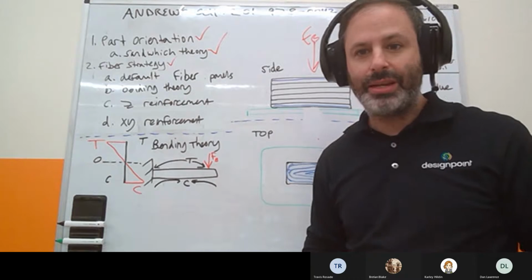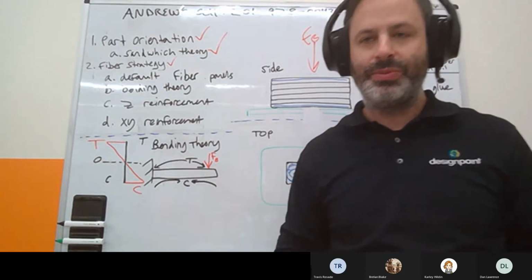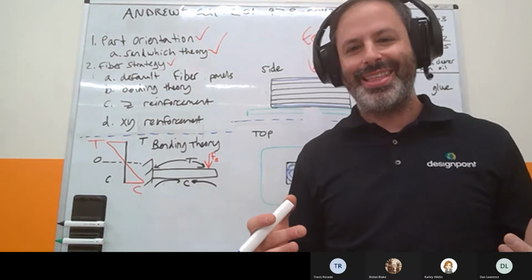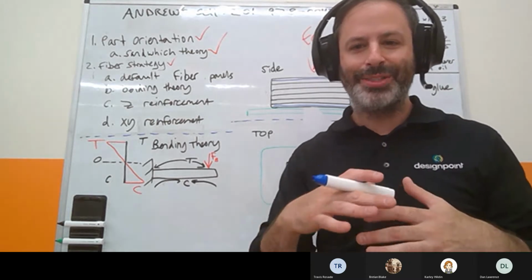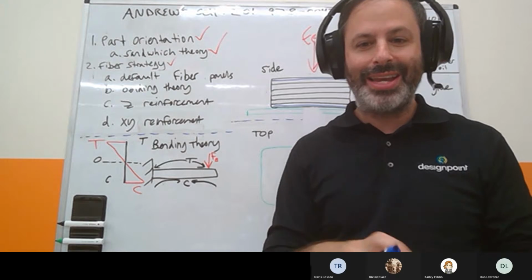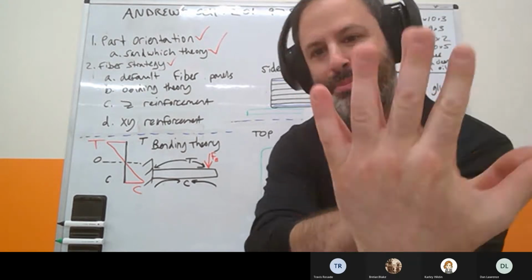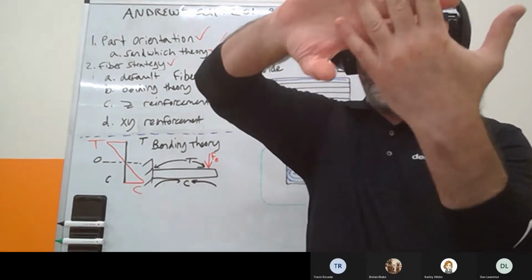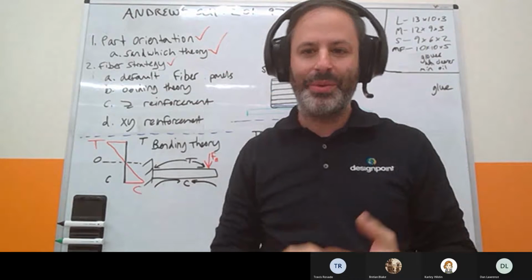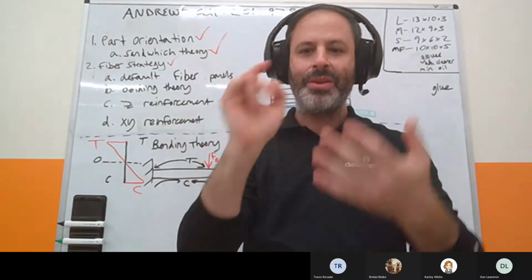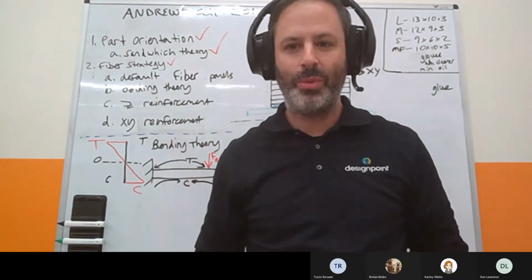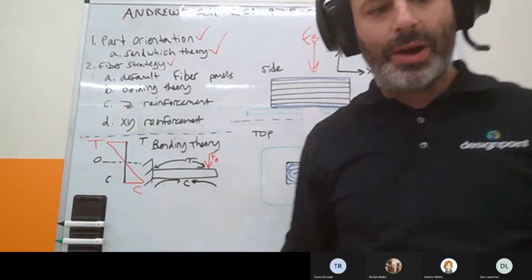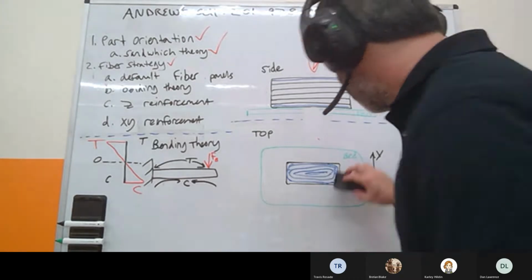And the way that I like to think about this is, think of yourself as a trapeze artist, right? And the fiber panels are your net. So do you want a net that actually lines up perfectly like that? Well, no, you might fall through the net, right? You want the net that's cross-hatched. So that's a good way to think of it. When the force is coming into Z, you probably want to think about using the more cross-hatched isotropic fiber panels. Now, let me draw that again.